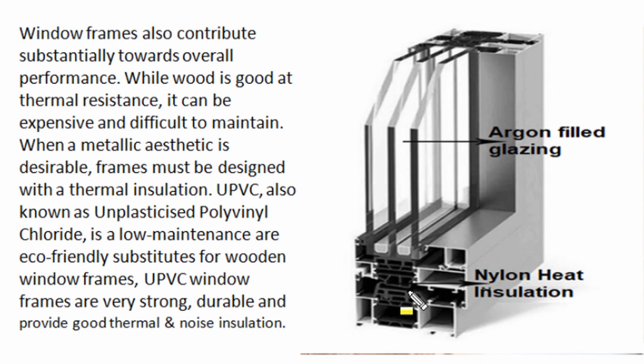So we use nylon heat insulation between panel and frame, and triple panel glazing with argon filling. Nylon heat insulation in a metal frame gives not only better aesthetic appeal, but also good energy performance with a low U factor and low solar heat gain factor.